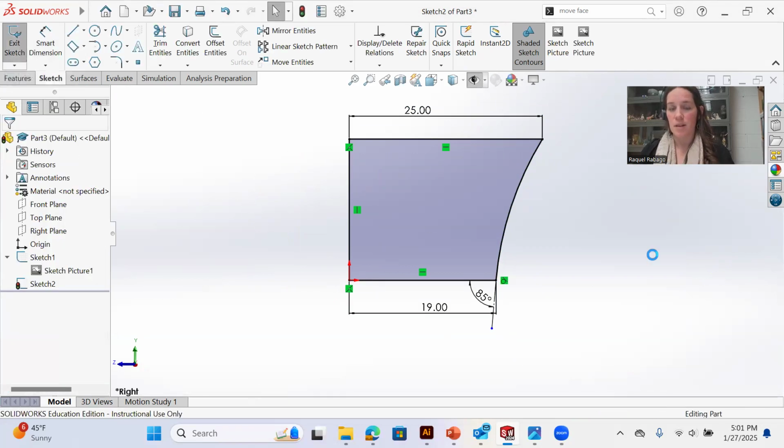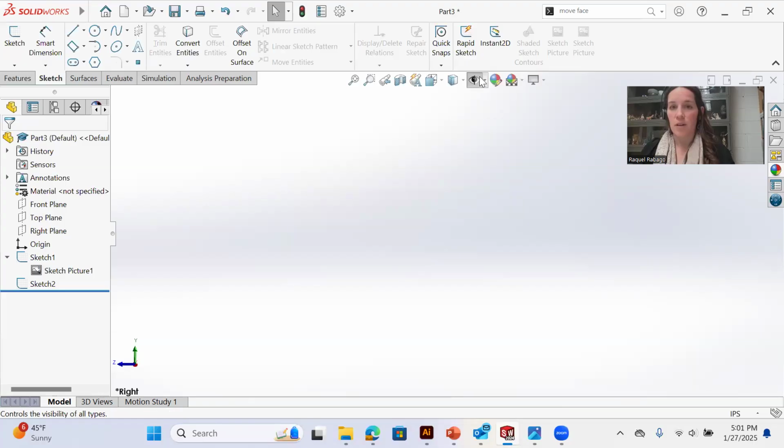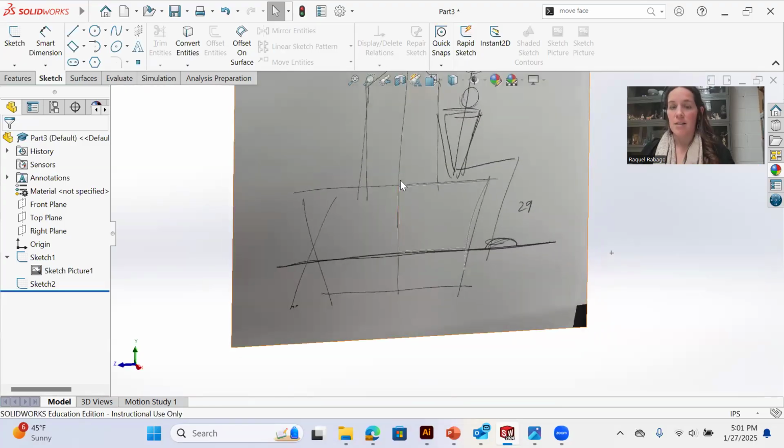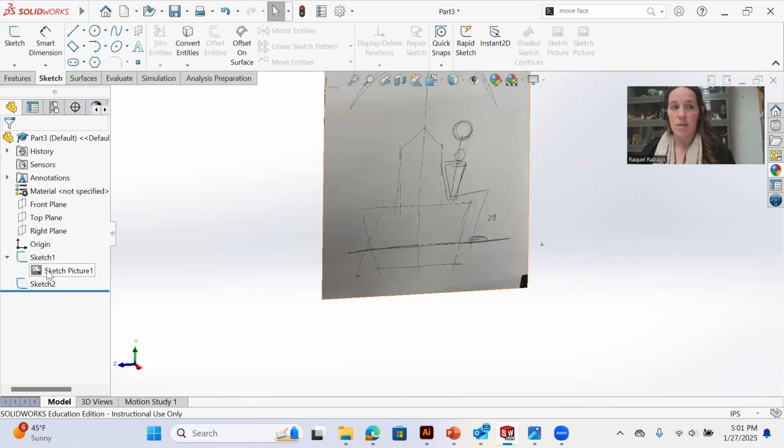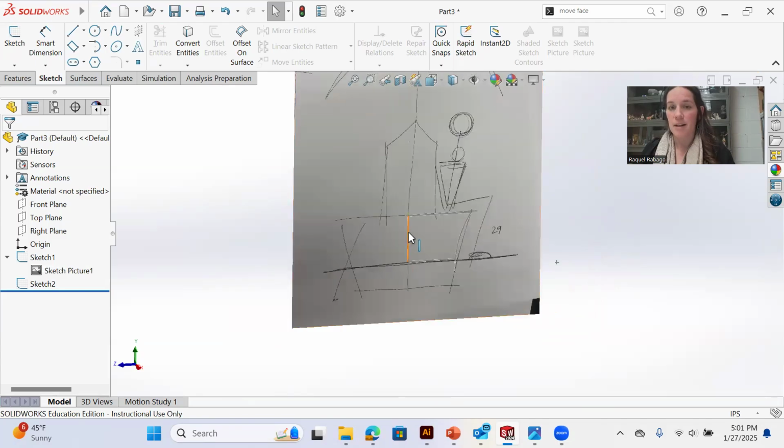So there we go. What you need for a revolve, I'll bring this back so you can see it, is you need to identify the axis you are going to revolve around. I kept mine on that y-axis, where I sketched that center line. You can use either a sketch line or you can create an axis to rotate things around. So a couple of options there.